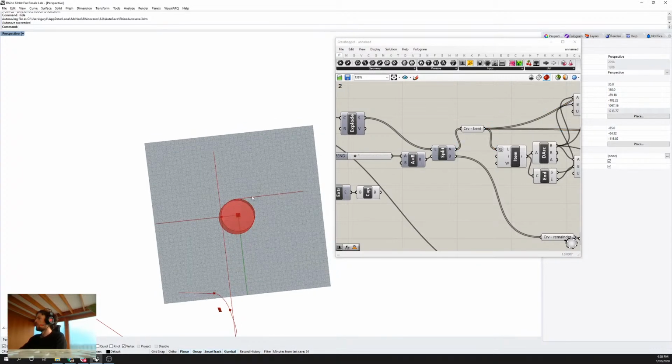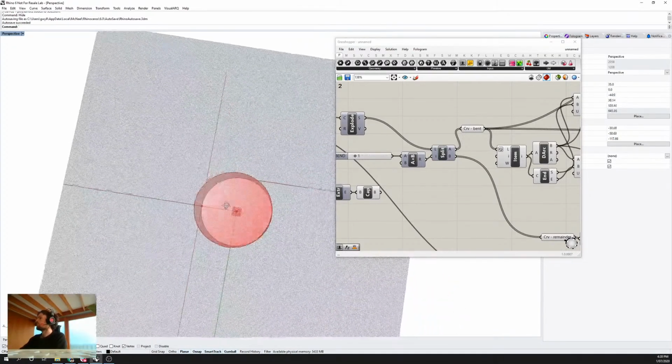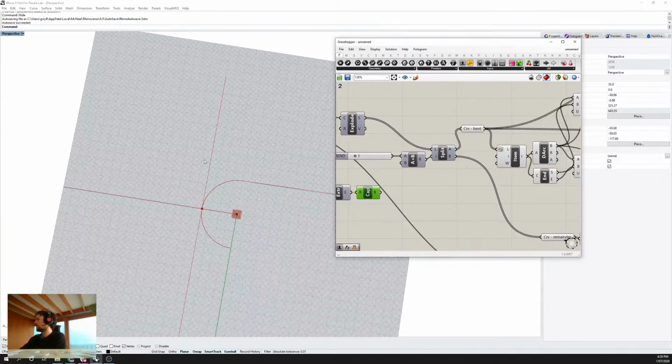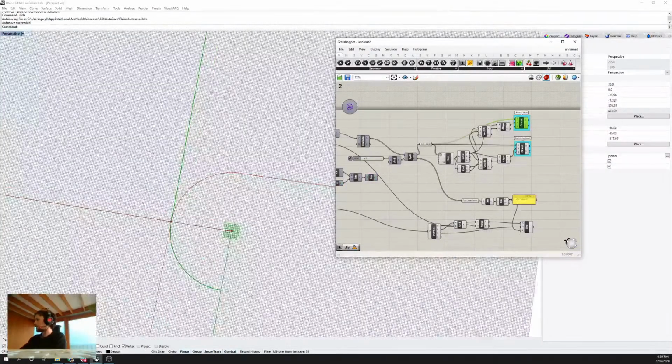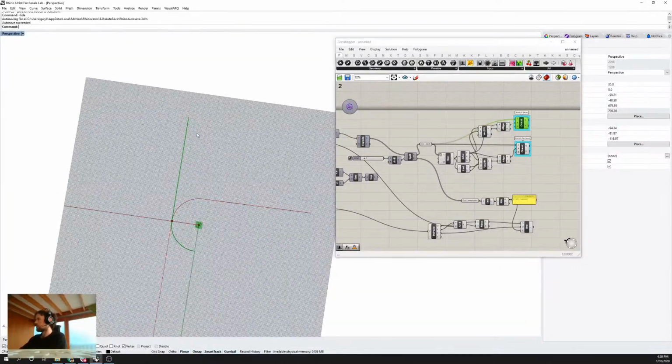Yeah, that's good. I think it's still actually slightly incorrect, and that's because when we're orienting this part, we're orienting it such that the bending arc now, if I hide this thing, yeah, you can see it there. The bending arc has been pulled around here. So this is not actually correct. If we bent this straight segment around, we would lose this amount of material. We would bend this pipe around and end up around here somewhere. And that's because we've rotated the piece around this axis with this radius, and so we've lost this amount of material.